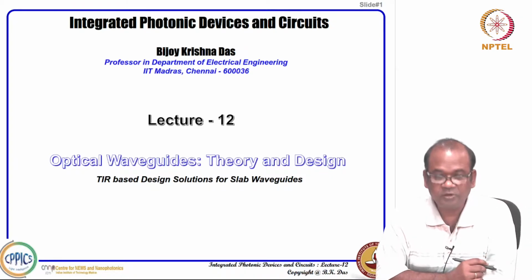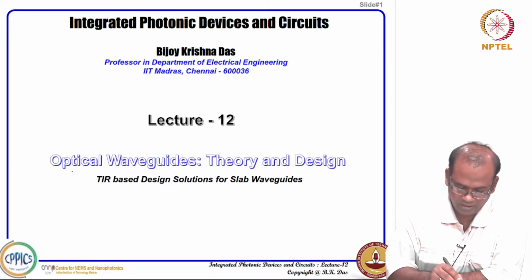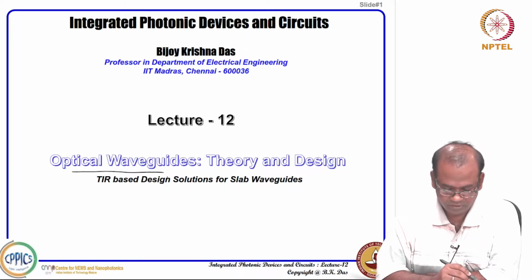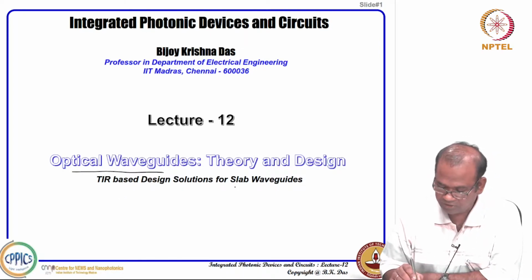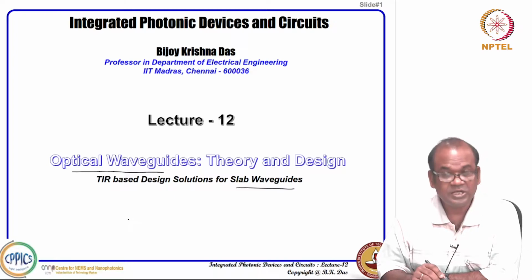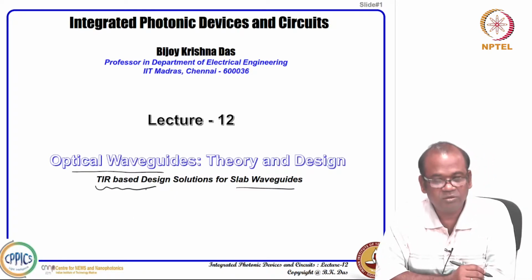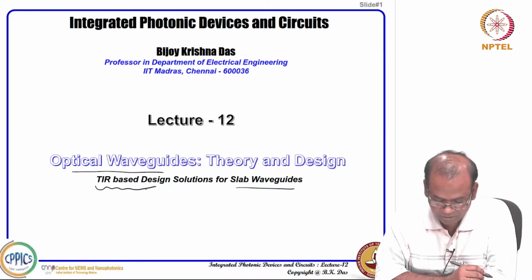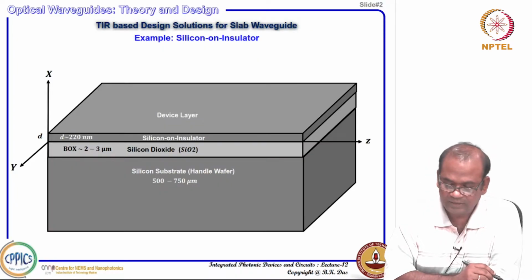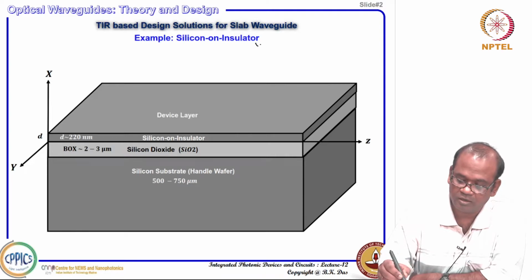Today's lecture I will continue optical waveguides theory and design. Specifically, I will be considering slab waveguides design solution. Of course, I will be discussing this based on the total internal reflection principle, and for that I take one example of silicon on insulator.